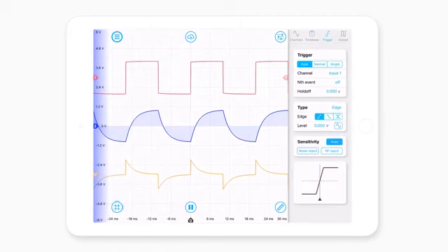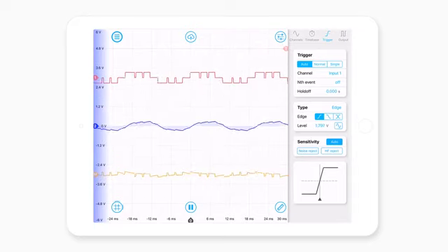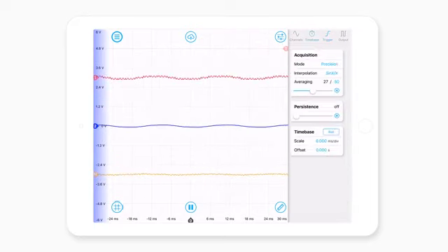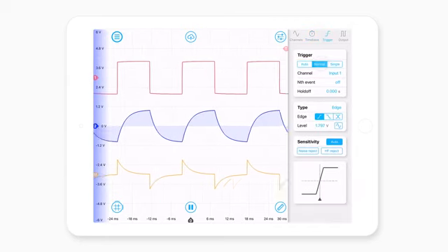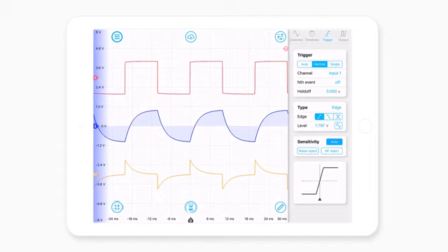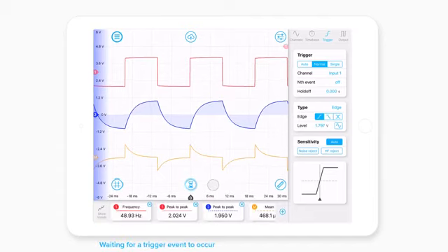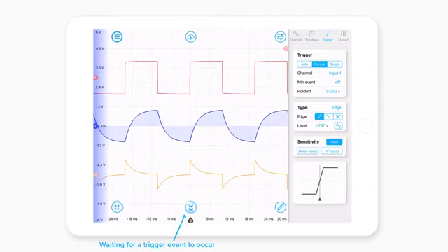The next settings menu that we're interested in is the trigger menu. So you can select between auto triggering. This basically means it'll always trigger no matter what's going on, so you'll always get frames coming in even if they don't look so good. I might quickly turn averaging off because that's a bit weird. You can go to normal triggering. And so you'll notice down the bottom now there's this little hourglass. This is indicating that the oscilloscope is waiting for an event.